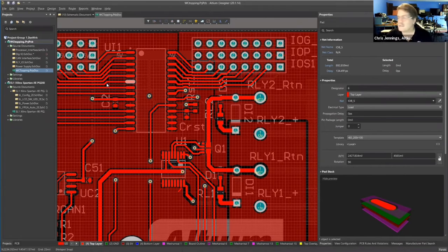With the BGA packages and a lot of the signals being brought down into the inner layers of the PC board, you need to think about having some test logic, whether in this case it's on the board or you put something in your schematics to give you access. As the designs get more and more complex, testing and integration is increasingly difficult and can actually cause a lot of time and delays. So consider having test logic added into your basic designs.